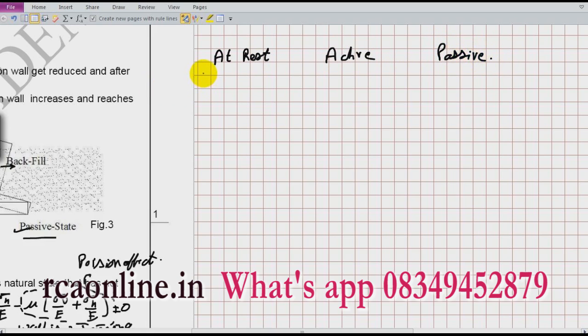Now, the coefficient of lateral earth pressure at rest is 1 minus sin phi. For active, it is 1 minus sin phi over 1 plus sin phi. And for passive, it is 1 plus sin phi over 1 minus sin phi.